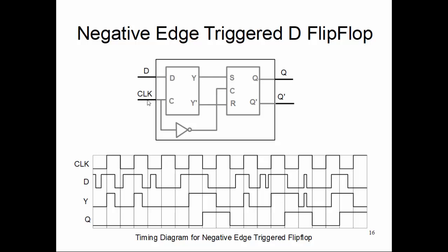Why? Let me explain it. So clock as a signal is always going up and down, repeated in a period. Now let's say D is independently just toggling its logic value. We don't have any control over it. Now you see that Q is not following D, right?